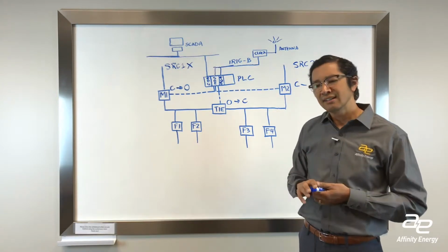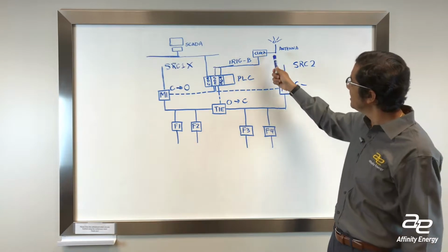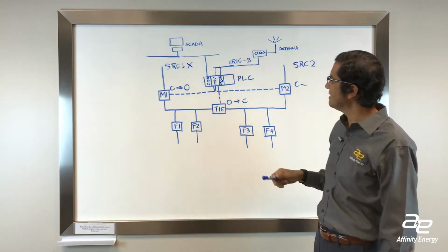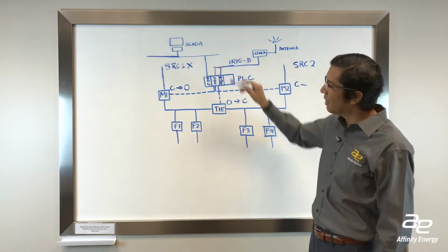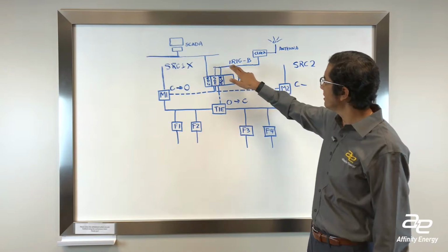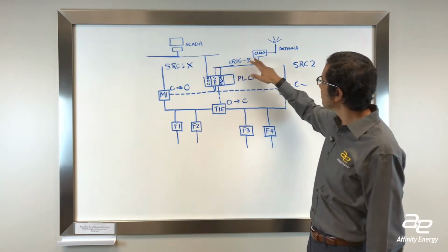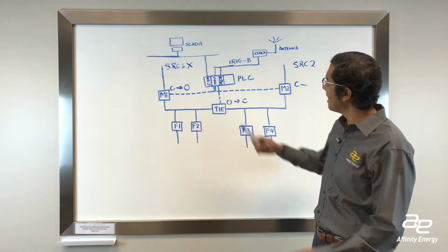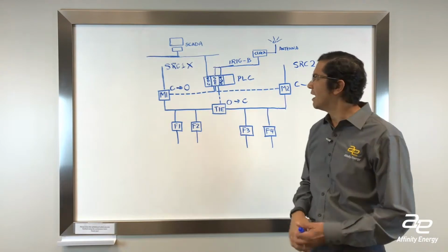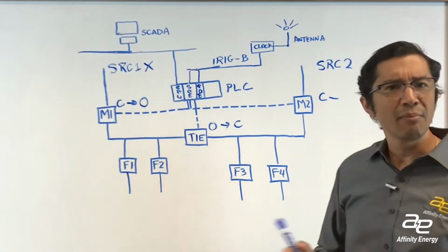It's a known time base that's accepted throughout the world, and once the clock receives that time base, you need to distribute that time to your devices. This protocol, which in the electrical industry and also in the automation industry is called IRIG-B, is a protocol that is used over coax cable to distribute that time signal to the sequence of events, or they could be digital input modules. The reason why IRIG-B exists is, A, it's deterministic.